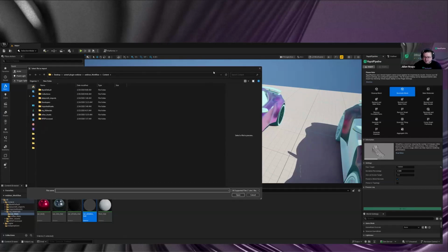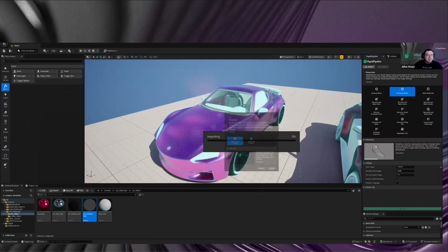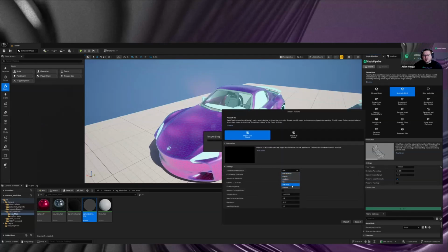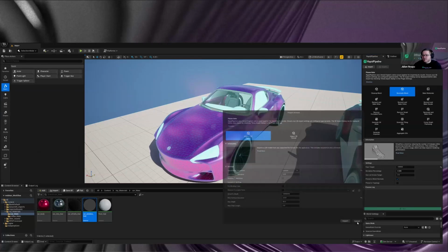If I double check here, because the presets are based on millimeters as well, what you get with a very fine, or in this case called extra fine, resolution is already on that level that you shouldn't see any blockiness anymore, even in the smallest screw or detail. If there's still an edge case, you can still go to the custom resolution and go very low in terms of the surface deviation, being very close to the original parametric surface. Then you should get a good, lifelike representation of the actual parametric curvature and everything.